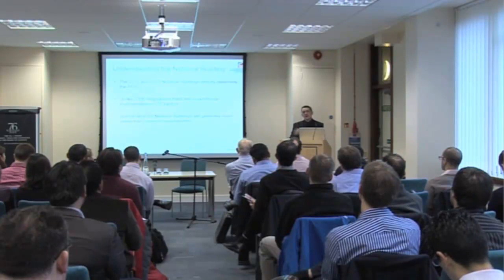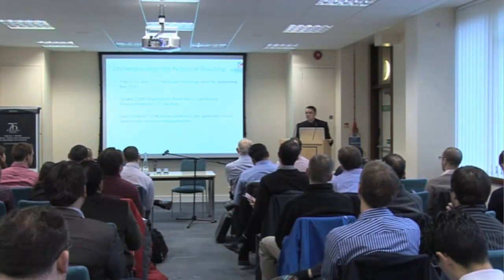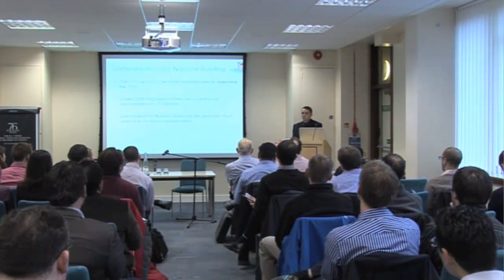One of the things I see as an advantage of this aggregate calculation method is that the notional building is based on a set of predefined settings. You've got a predefined fabric setting, system efficiency parameters, and air permeability parameters. So if you can design your building to match those properties, you should have a compliant building. If you were to build the notional building, that building would comply. So it gives users a template. These are the areas where, if I'm doing poorer than the notional building, I'm going to have to make up that saving elsewhere.